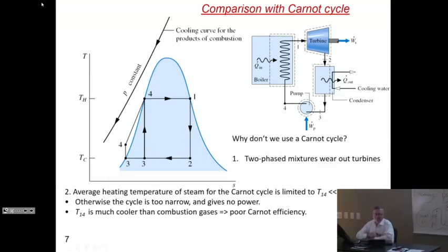Okay, the next step then is to try to get a Carnot cycle out of a Rankine cycle. So if we were to try to get a Carnot cycle in a TS diagram, we would simply go from 1 to 2 in an isentropic, and that hasn't changed, and condense it, but instead of going all the way to pure liquid, we would stop halfway so that the pump and the generator would get us straight from 3 to 4 back to 1.